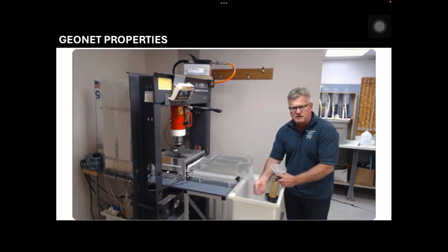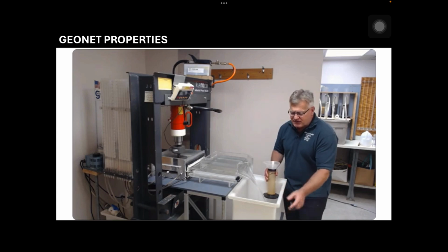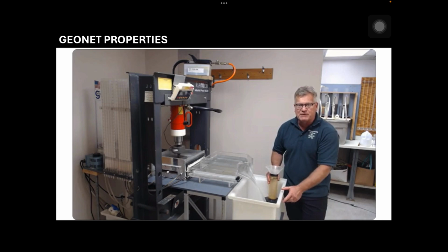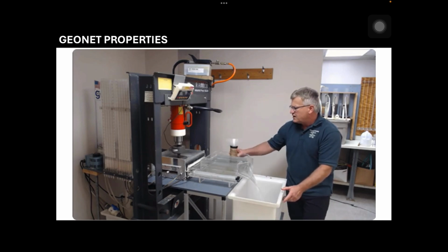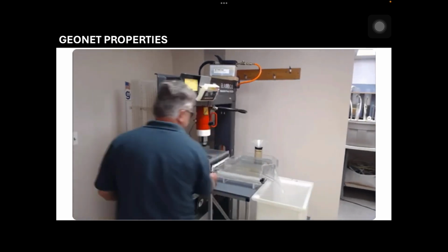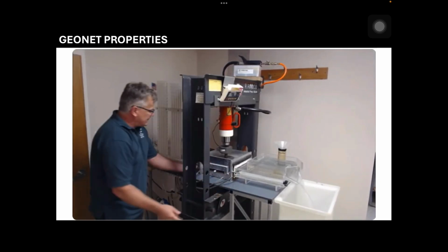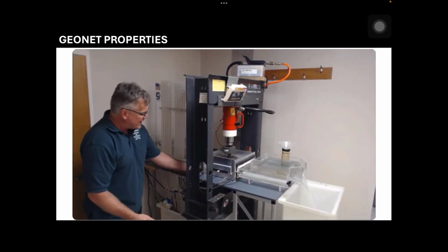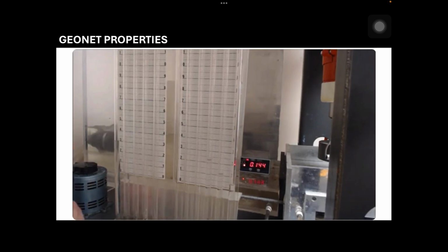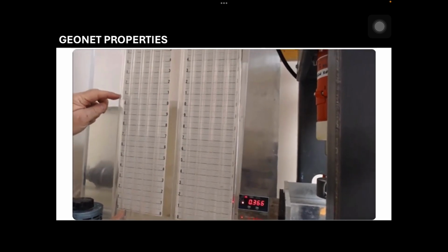Obviously, the higher the flow, the bigger the bucket you'll need. Sometimes we close off this bucket with a valve and subsequently collect that with respect to time. You control the gradient typically off of manometers. This is the one for the outlet, and this is a similar one for the inlet. You have to make sure that there are no air bubbles in the lines, so that you get an accurate reading with the manometers.